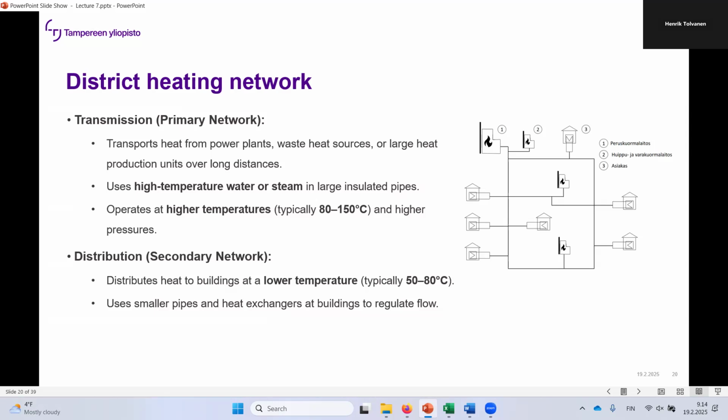So what it means is that you have less heat losses, but then you have more pumping. And the main problem, of course, is: does the customer have in the secondary distribution network, so kind of like the connection point, that's pretty much the transformer, you have the heat transfer unit. Does the heat transfer unit have the capacity for operating under a lower transmission network supply temperature?